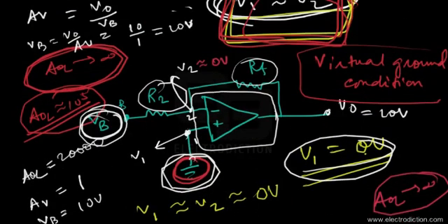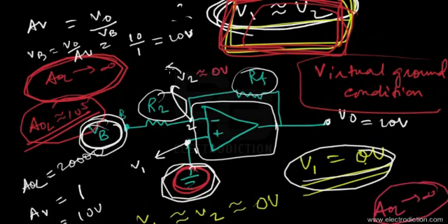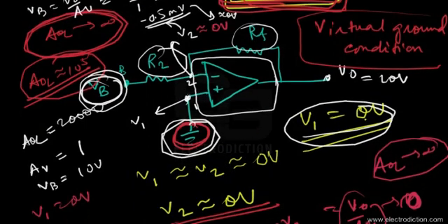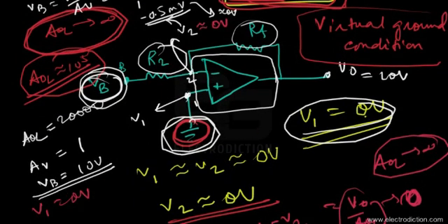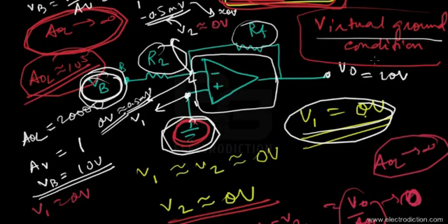So over here, at the terminal V2, we have a practical voltage of about minus 0.5 millivolts, which is approximately equal to the ground voltage. So you can see here, even with an input voltage of about 10 volts, the voltage at terminal 2 is approximately 0.5 millivolts, which is very small, and approximately equal to the ground voltage. So this is basically the condition of the virtual ground that I was trying to cite to y'all by means of this simple practical example.